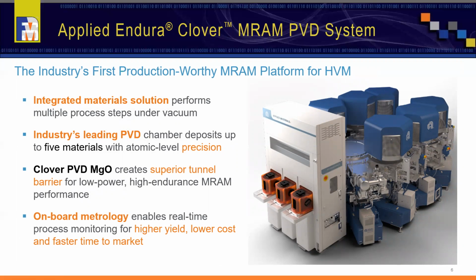For the magnetic tunneling junction, the deposition of films, including the MgO layer, is done on our Endura Clover system. The system can deposit more than 10 materials and form magnetic tunneling junction stacks that are more than 20 layers. This is done with atomic level thickness control and with onboard metrology to control and monitor the process.